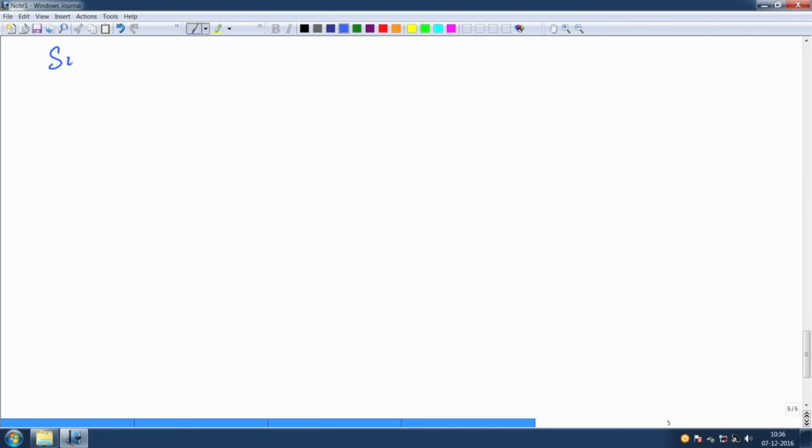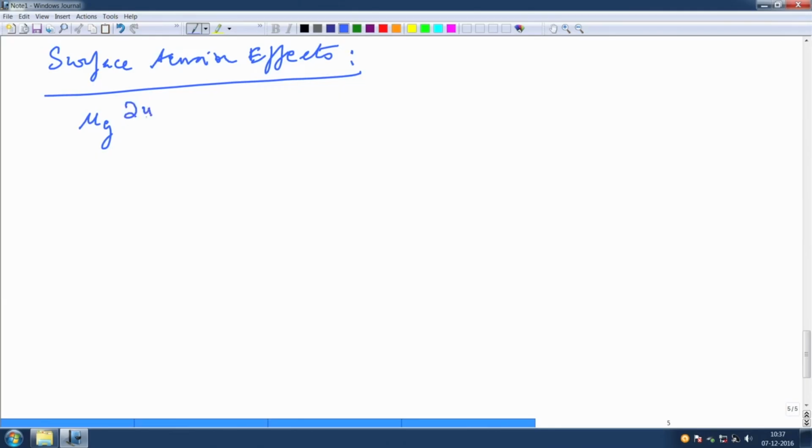the surface tension effect also. Remember, we said that the surface tension effects are negligible because of the simple reason that there is no variation of temperature across the interface, but some people have included the effect of surface tension. If you recall your initial classes, this is what happens: gas interface is equal to mu L at the liquid side of the interface, and then there is a d sigma by dx.